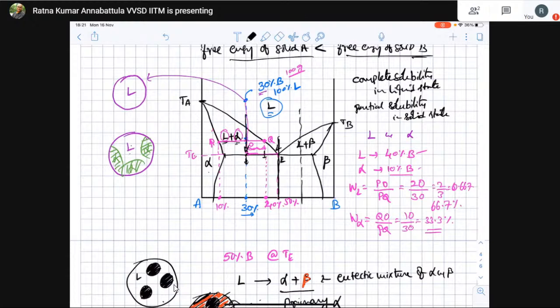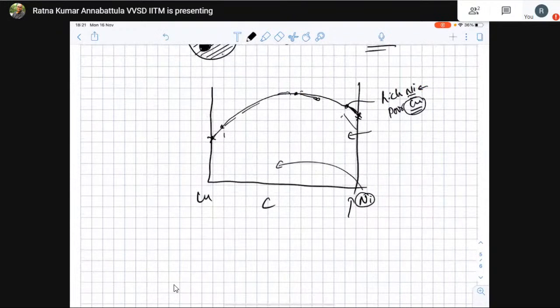See, solid solution is nothing but you are actually adding impurities to a pure metal, right? And as I have explained the strengthening mechanism here, that is mainly because you are adding impurities to your parent phase. Okay.